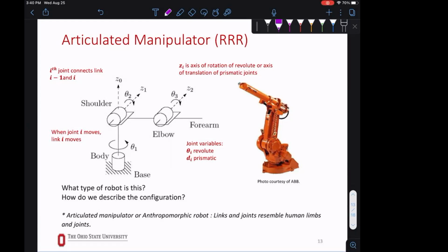We also have an axis that the joint is rotating about, so it's rotating the link. So let's look at my arm. This joint is moving this link, right? So a joint always is moving a link. So you can't have a joint at the end of the chain. So what is this doing? Here my wrist is actually moving this part, which is the most important part, the grabber, the end effector, right? So this whole arm is built so the end effector can perform its task, right?